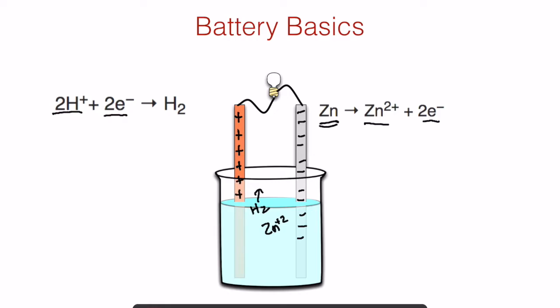What we're then going to see happen is a voltage or energy difference exists between the two metals. The voltage will be the change in energy per charge between those two metals. The voltage is going to be determined by the type of chemicals and the concentration of the chemicals inside the battery. Once we have a negative and a positive with an energy differential, we can have the electrons repel each other through an object such as a light bulb and transfer some of their energy into the bulb.